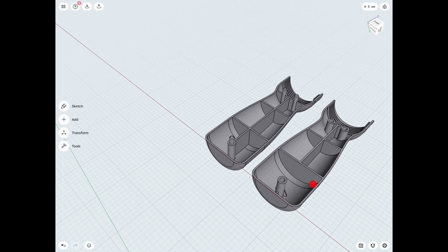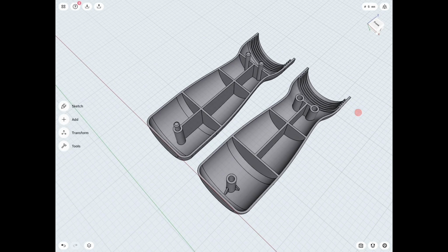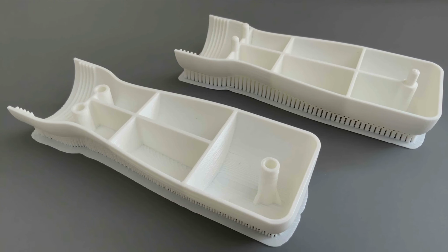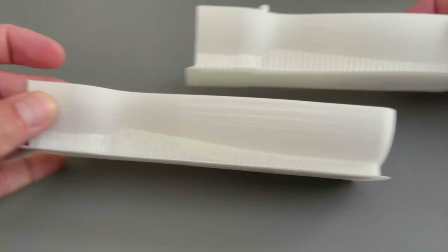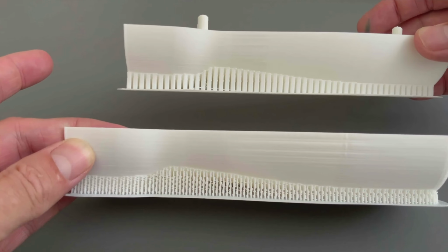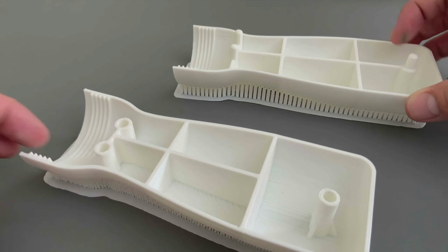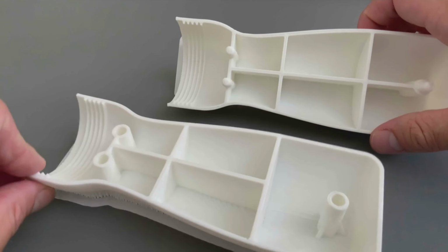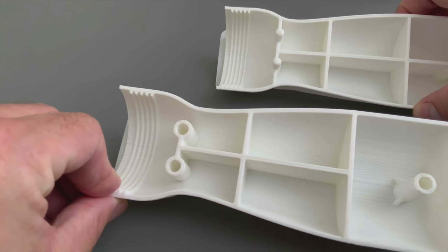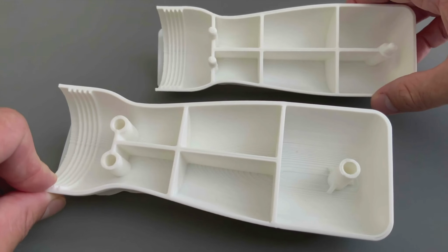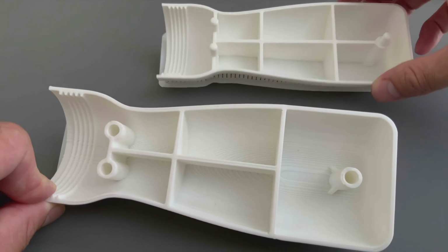I used here this vessel simply as a demo to also show how we could create a web and how we can add ribs, and also talk about the problem of mating. In the video you can see I have everything nicely printed. I decided here to print the support outside, so I can shave this off and then with a sander, if needed, clean this up, because my important focus was the threading and also the connection parts.